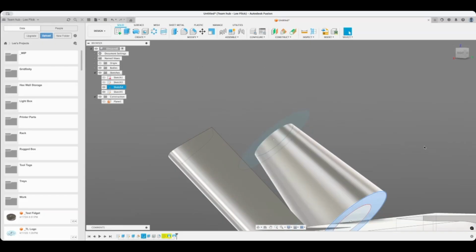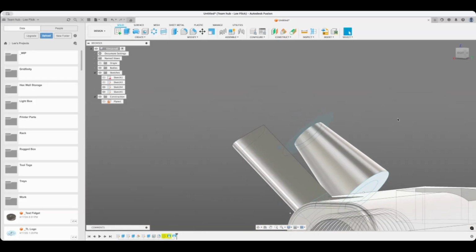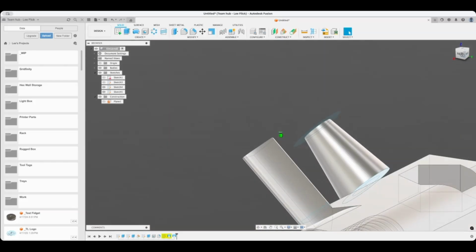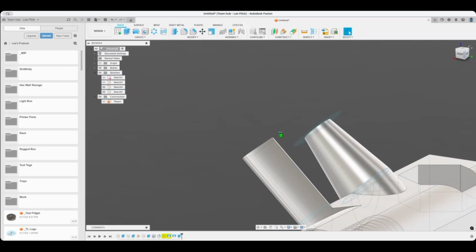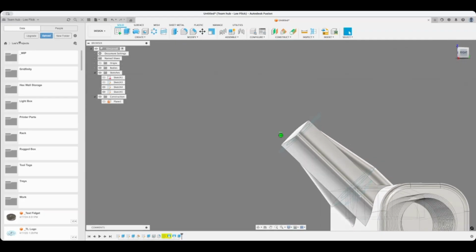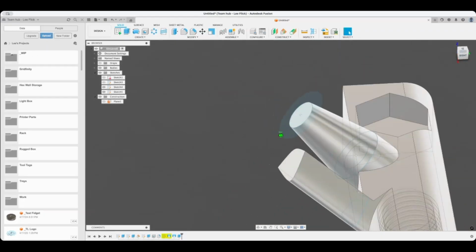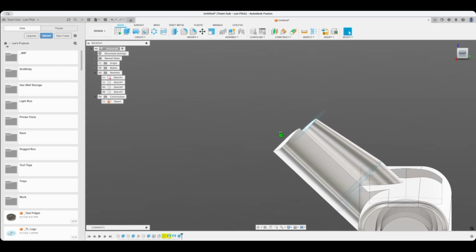Click the surface, hit delete. No, it's not going to let me. How about this one? Because maybe two surfaces? No. Okay, so let's try push pull. Sometimes push pull will work. Push pull command, hit that surface. Join. Looks like it mirrored it to taper the other way. That's pretty cool though. It took the straight portion.